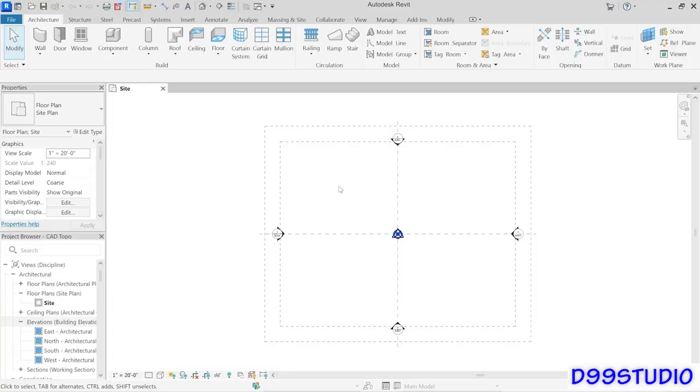So if you're working with a civil engineer in your projects, then there's a pretty good chance they're working with an AutoCAD-based product like Civil 3D or just the main version of AutoCAD. In that case, they might be generating the site plan information, the civil information, as a DWG file. We talked about bringing in DWG files in an earlier video. Well, I want to show you that workflow here, very specifically related to using it to create topography, because some of the settings we're going to choose are going to be a little bit different.